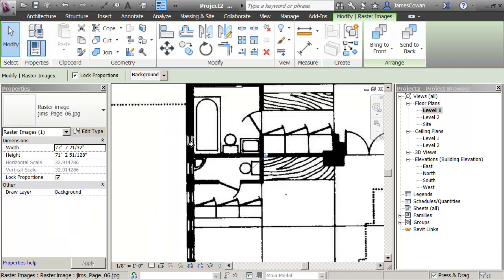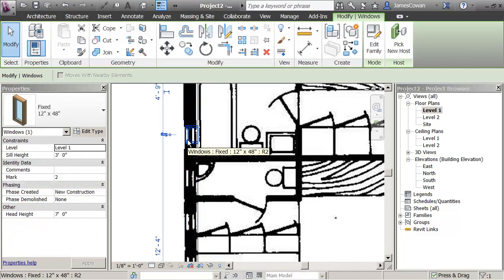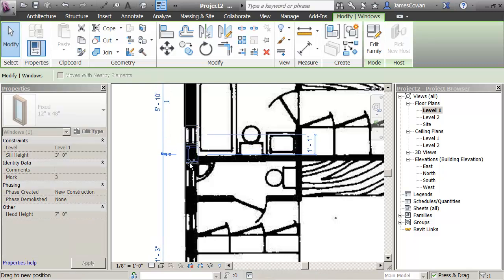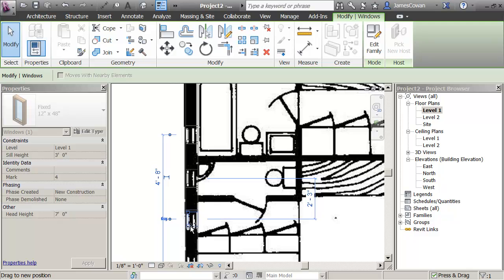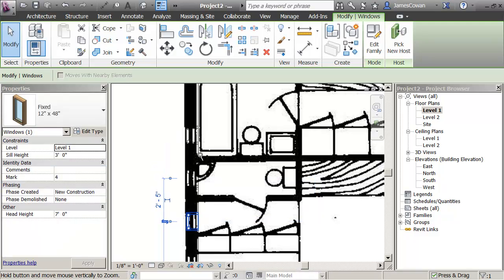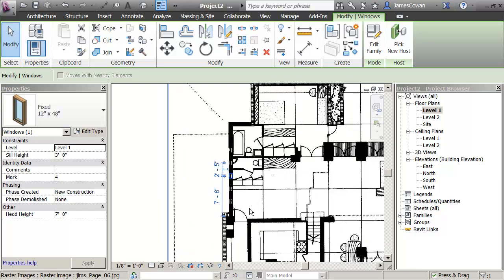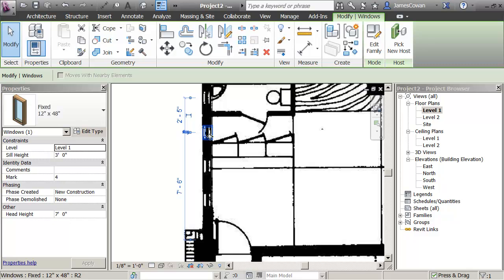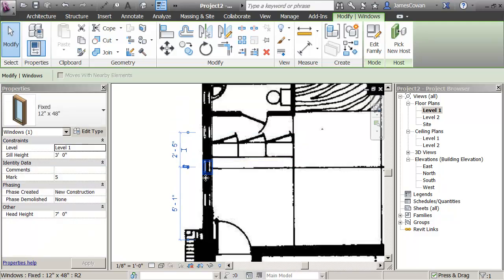If I select the window, so if I pick the window and I hold Control and Shift and I drag, it's actually making a copy, and I can place it, and I can continue to hold Control and Shift and drag. Let me get a little bit closer to here. So I'm over there, Control Shift, and it's selected, and I'm dragging and it's making a copy. And one more time.